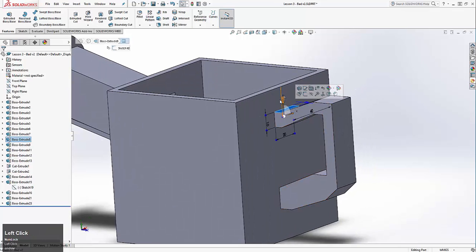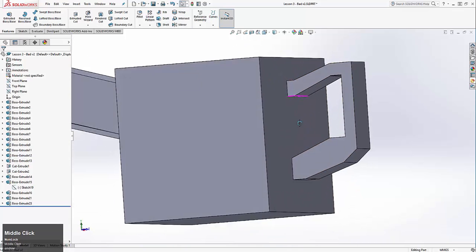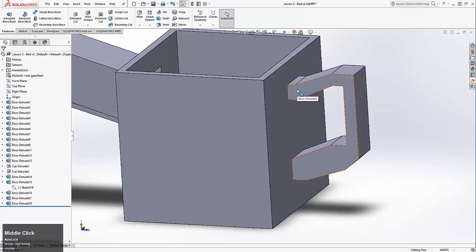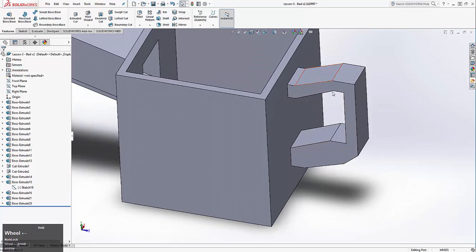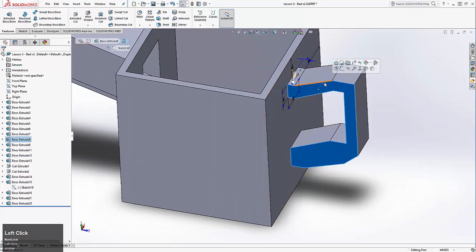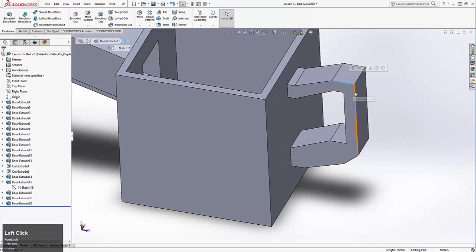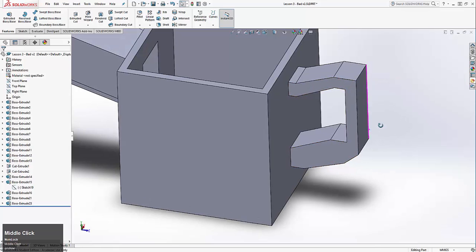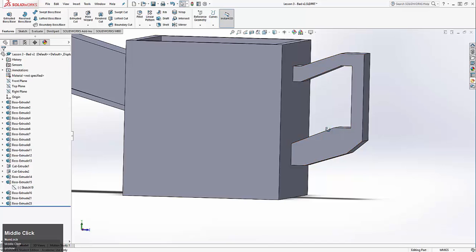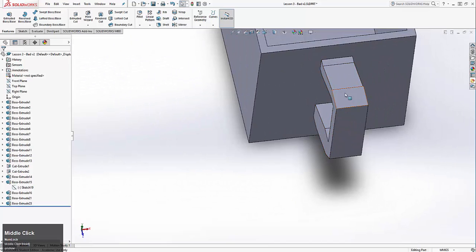There's very little support. So if you had a fillet here or here, that'd be good so you could spread the weight distribution a little bit better. The edges are not rounded, so this edge would be good to be rounded because if you're going to grab it, you don't want it to be sharp. This bottom part's a bit thick. It's also strangely wide.